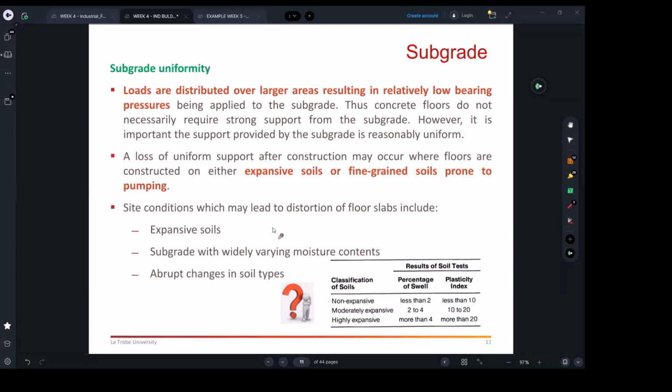The point from what we're talking about here is you need to know about the soil condition or the subgrade condition, because it will let you budget it correctly and time it correctly. You don't need to get surprises. If it was written in the soil report, you should have known about it when you priced the job, so you can give the correct timing and the correct budget needed to get it done. These are good notes for you to know.